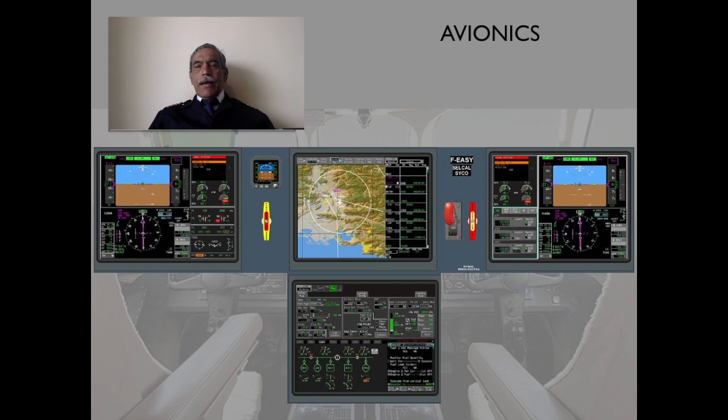Okay, let's recap a little bit as to what we learned about easy cockpit. I had taught you earlier that a lot of other display systems have been reduced to four basic displays in an easy cockpit, and each display is configurable in smaller windows in two-thirds and one-third and half, and these windows can be combined in different proportions, different ways by the pilot for the appropriate phase of flight.